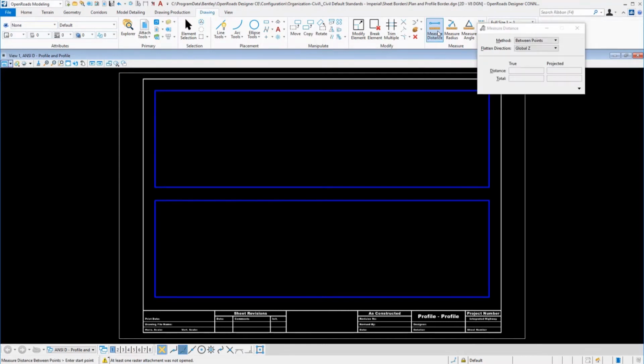And let's first take a look at making sure that our title block is a real size. In other words, a real piece of paper size. So if we take a measurement vertically, I have 1.833 feet. If we convert that to inches, that's a standard height. And then we have a width of 2.833 feet, which is a standard width for an ANSI D sheet.